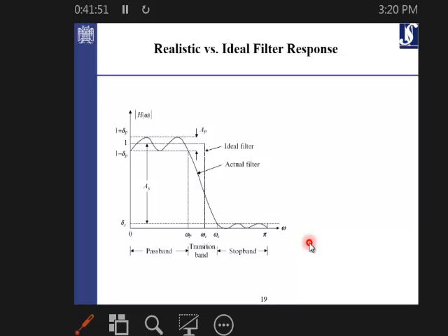We don't have any information about that. If we know exactly what the filter is, we can calculate by hand that the phase should finally go to this, but how it changes, we don't know. In the FIR case, we know that the phase changes linearly, that's all.